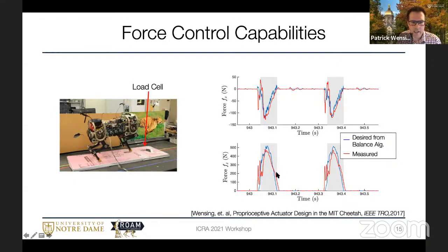And I'll emphasize here, the robot doesn't have feedback from the load cell. It doesn't have a load cell under its feet either. This is just open force delivery. And it looks reasonably accurate, but I think the more impressive thing here in terms of being highly dynamic is that we're looking at going from 0 to 500 newtons in 40 milliseconds and then back, right? And to put that in context, the blink of an eye is around 300 milliseconds. So these are just fast dynamics.